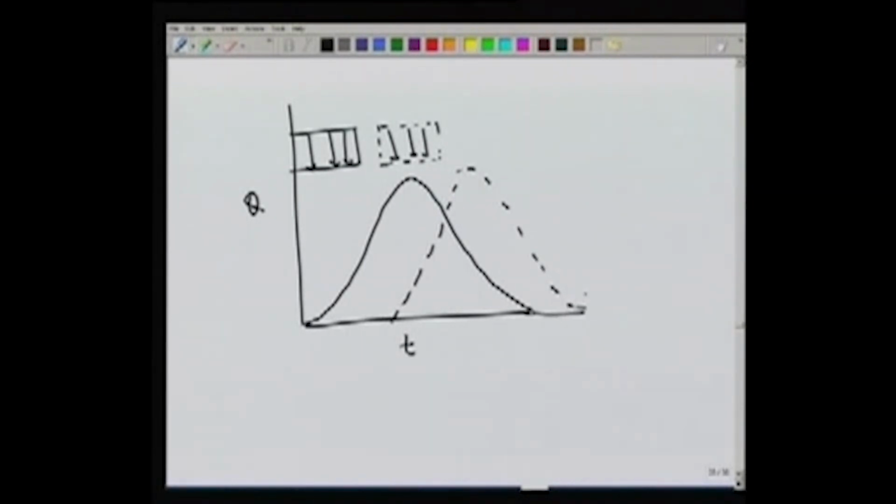Like this. So these two hydrographs, this and this, will be the same if the effective rainfall hydrographs, ERH, are the same. So that is the principle of time invariance: no matter where in time the effective rainfall occurs, it will produce an identical hydrograph. The second principle which we have is the principle of linearity,